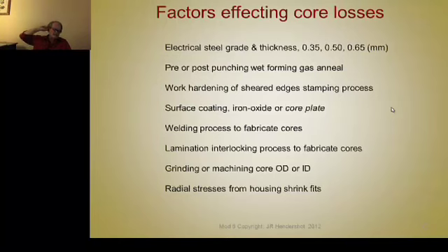They have very close fitting OD of the laminations and ID of the housing, and they bond them in with Loctite or with thermal silicon. Thermal silicon not only bonds them, but it dampens them a bit for noise, and thirdly, it provides a little better thermal conductivity between the laminations and the aluminum housing.